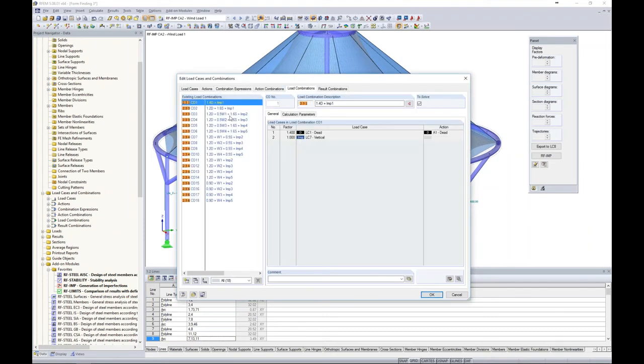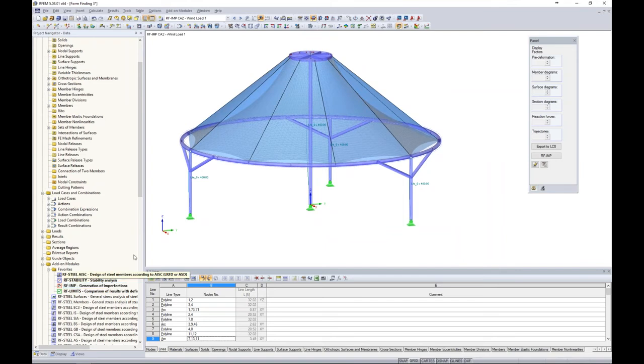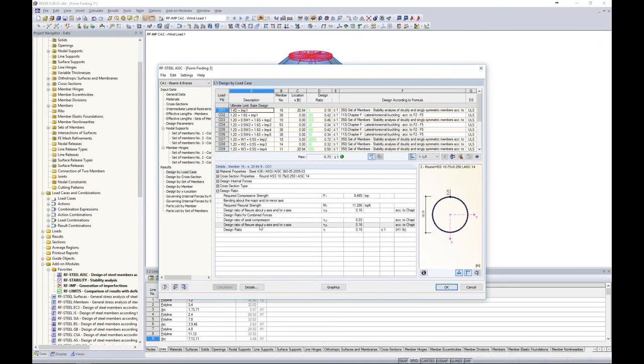Then under load combinations, you can see all of the different imperfections applied with their associated load cases such as wind load. For example, LC2 is the imperfection from wind load 2 applied only to wind suction at column. LC10 is wind load 3 applied only at wind pressure between column. So that's just kind of how we can apply those imperfections to the rest of the structure. Now, lastly, we can run an analysis, a code check here from our analysis according to the AISC module, for example.